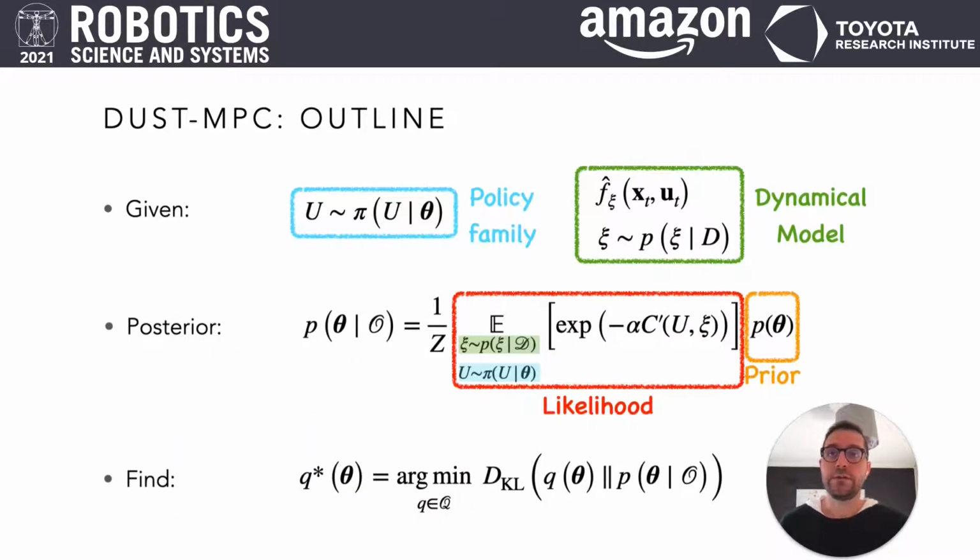SVMPC assumes that the dynamics model is known and stationary and relies on the closed-loop robustness of the controller to compensate for any localization errors. Moreover, and perhaps more importantly, it considers the future state predictions given by the dynamics model as exact point estimates, which may undermine the performance under more severe model mismatch.